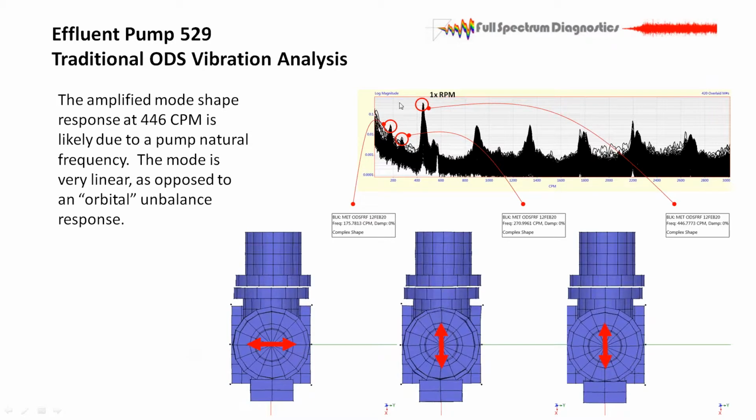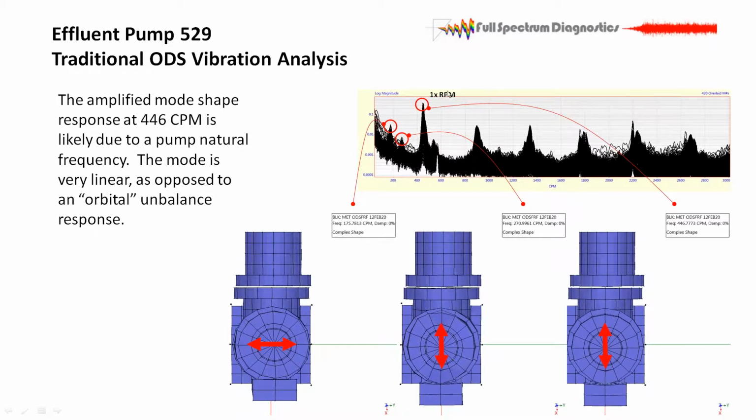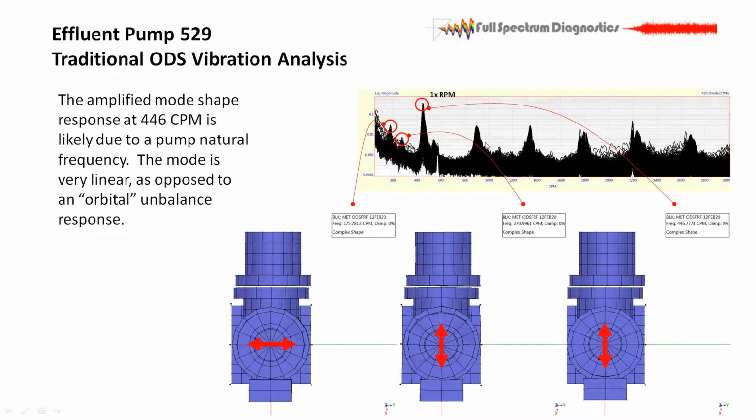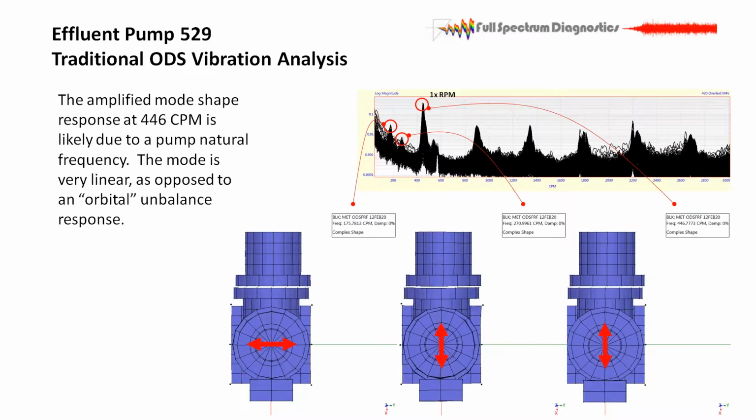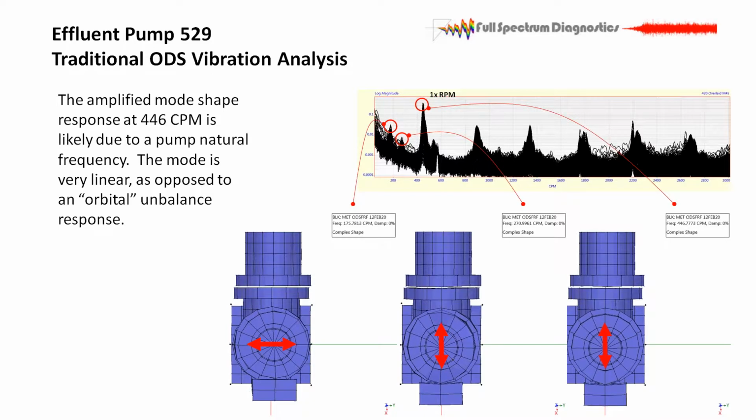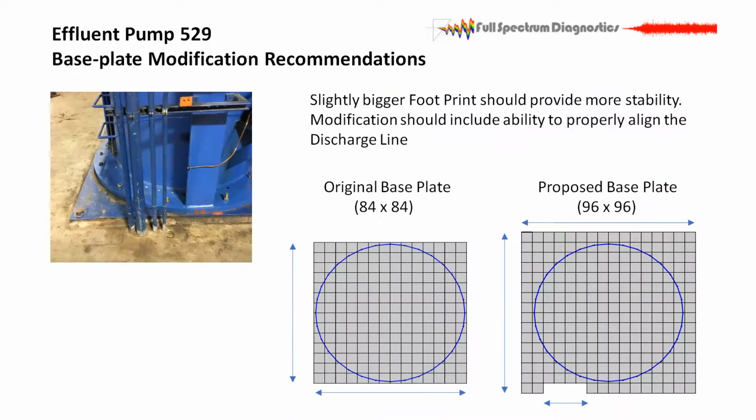Okay. These two levels, on a log scale, they look bad. On a linear scale, they're in the floor noise, as well as all these other peaks. So really the only one of concern is that 1 times RPM peak, and what do we do about it?